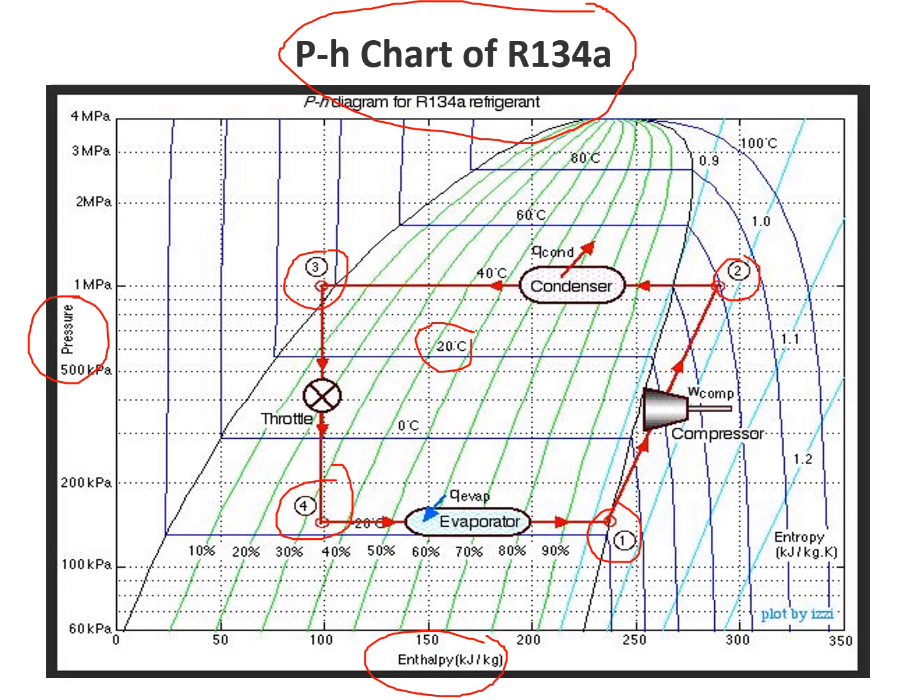Let us suppose at the suction to the compressor you measure some temperature. Definitely we have thermocouples to measure the temperature. If you know the temperature, and also you know the pressure at 1, which we can measure by some device, then you get some temperature and you have to follow that temperature line in the pH diagram like this. Let us suppose this is the temperature. So that temperature you have to mark, and this is the pressure. You see, this is the point.